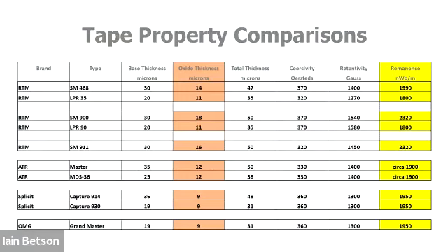This is what I'm saying, is when you start to have to work on overbias figures, sometimes you have to work out, taking this information, how much you're going to overbias a tape for, based on tapes that have got similar construction, oxide thickness, backing thickness, and all those kind of things. We look at Aircapture 914, 930 is their long play version. They say in their literature it is similar to Ampex 456. Ampex 456 is same as ATR's master tape. It's near that. They do publish a remnants figure of 1950, but their oxide thickness is down to 9 microns, so you're not going to be able to push a lot of level onto that tape.